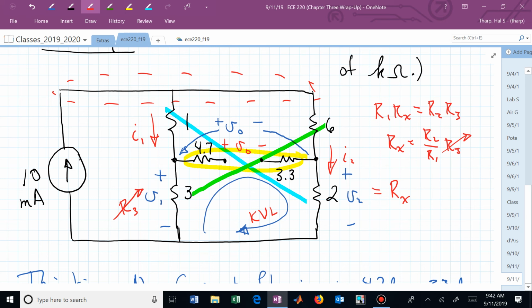So look at that and make sure it makes sense to you. Now, just say there's an I7 going through 3.3 and an I8 going through 4.7. And those currents are both 0. So from Ohm's law, you've got 0 volts dropped across those two resistors. That means the red V sub 0, we can expand, since there's no voltage drop, and it's effectively the blue V0.